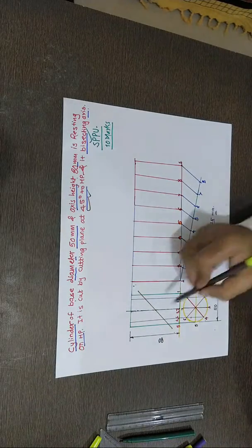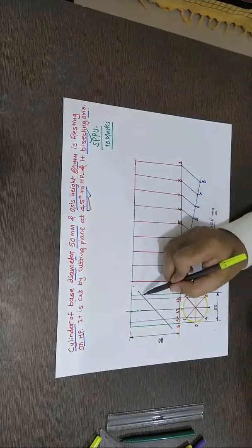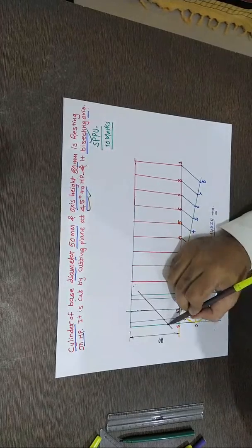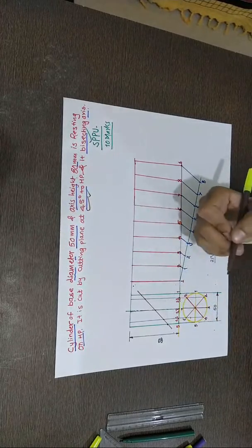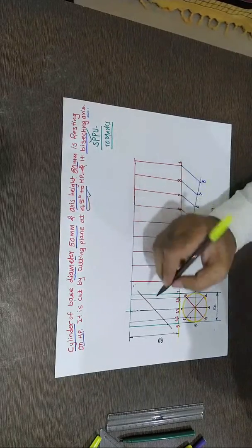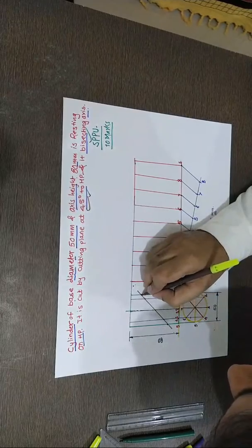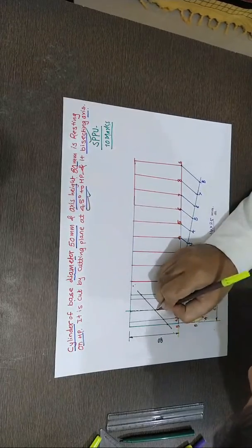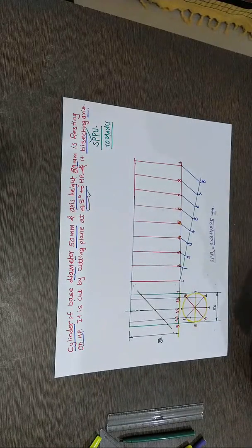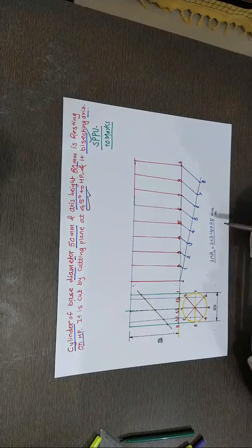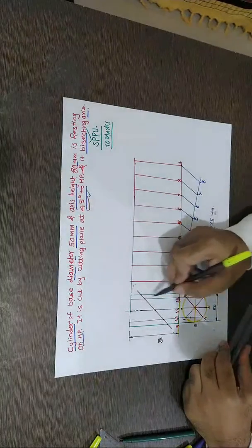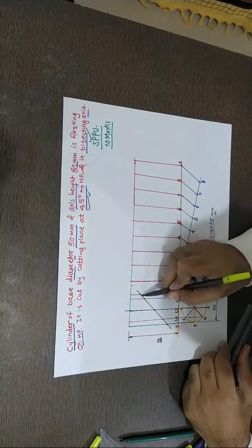Now same, this cutting plane cuts the different generator. Now it's not edges, the generator means a line which passes from this corresponding points of base and the top face surface. So now this intersection is this first, second, this is again 2. So we have total 8 parts. So very logical. Just project all those points on respective generator on the development. That's it. So that's very simple. This is 1, intersection 1. So develop